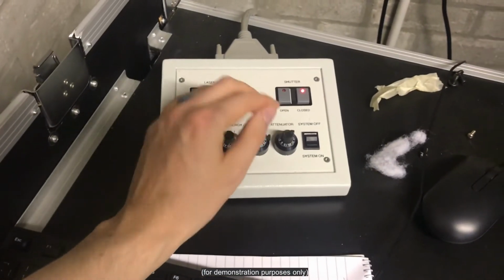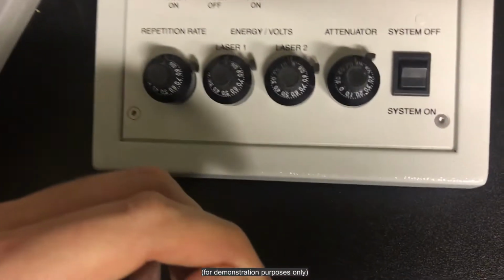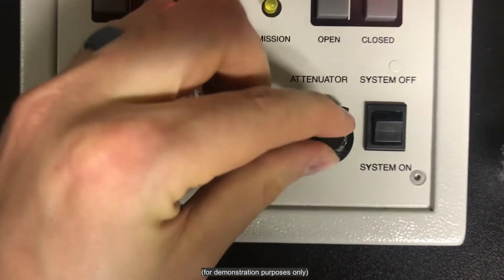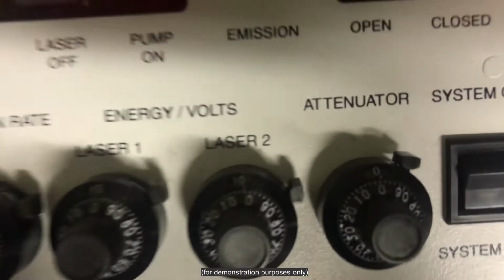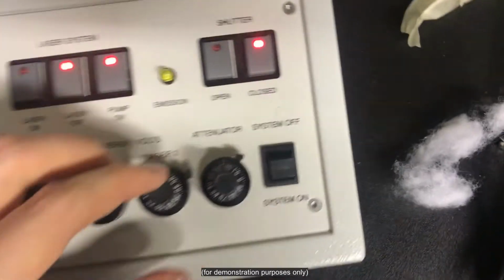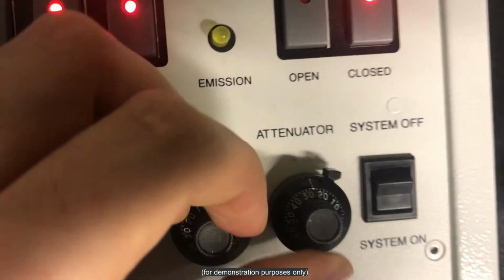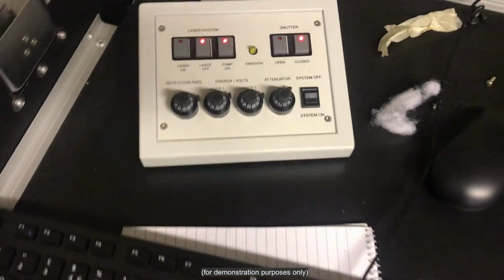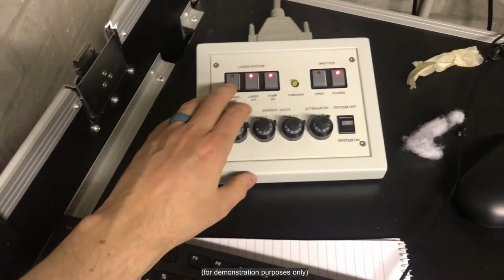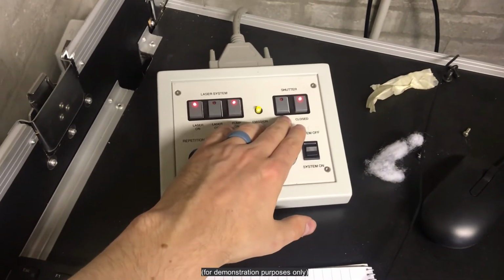And so we can set that, and typically when you start the laser for the very first time, you want to reduce the attenuator right down. And so just do that by turning this to the bottom, and you can see there that it's reading 0, that's in percent. And we can go up, and we're now at just about 13%, something like that. Okay, we're now ready to turn the laser on, so the laser will be now firing, but it's not emitting anything because the shutter is closed.